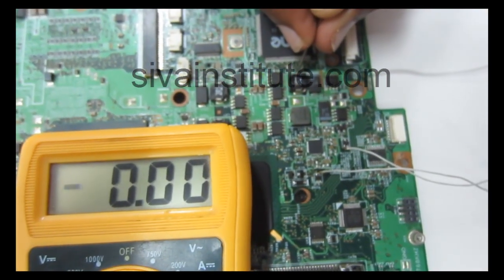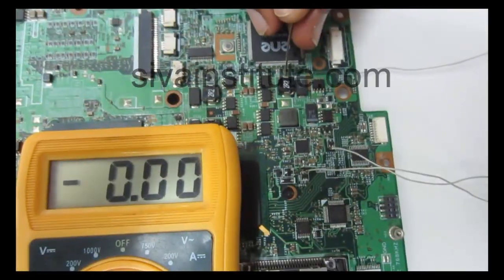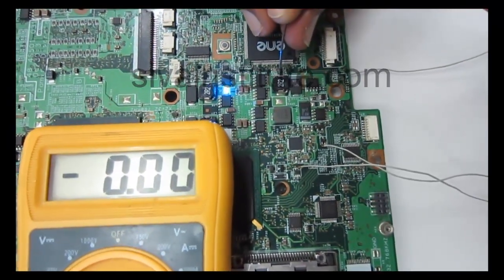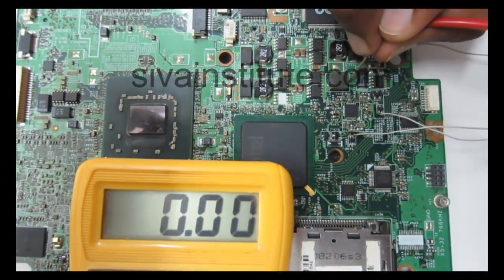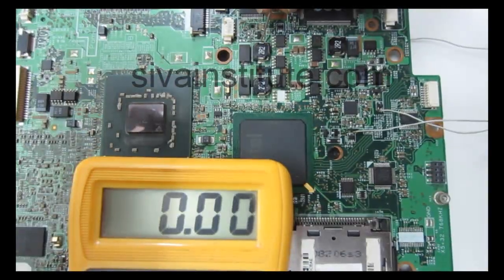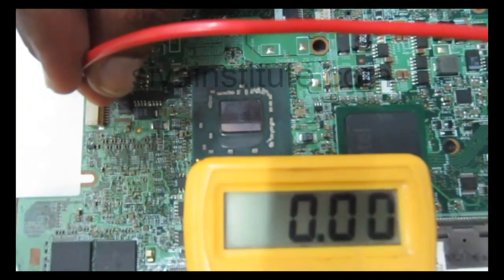Now I disconnected S5. Now I will connect the S5 connection. This voltage will come after the S5 command. I will give the S5 command. See here, 3.3 volts is okay. No 5 volts, but in some sets this voltage will come. No voltage at this point. That is the memory supply. No voltage at this point, and this voltage also. No voltage at this point.